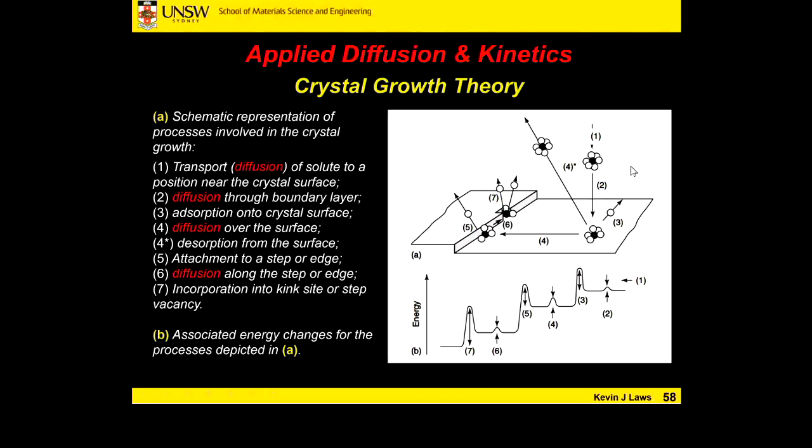Okay, or there could be a chemical concentration gradient that affects its mobility through this boundary layer. So we have to be mindful that there are surface effects there. And I guess it's similar to our gamma parameter, our surface energy parameter for the nucleation phase. Right? There's always some kind of stress or something going on very close to the surface, which this atom has to also overcome to be attached to the surface.